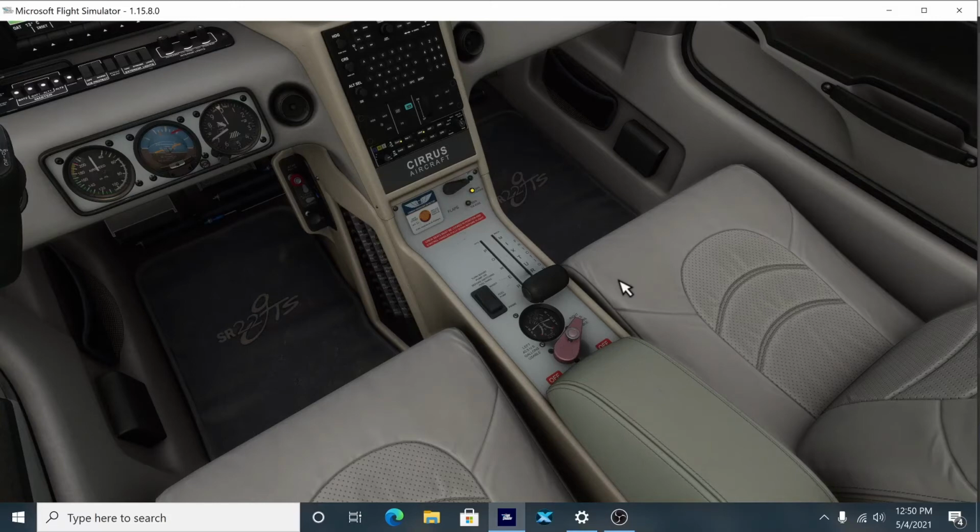Now this is what I was talking about with the fuel pump. There's only a command, or the hardware command will only work the prime position. So if you go up to the boost position, it's actually going to take it to prime. And when you go to the middle, it sends it to off. And then when you go down to prime, it goes to prime again.